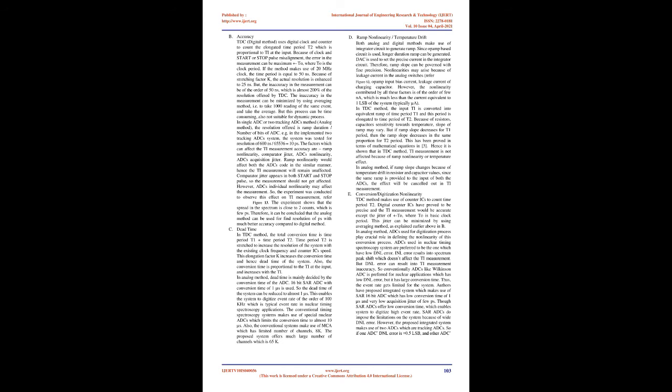In single ADC or two tracking ADCs method, analog method, the resolution offered is ramp duration/number of bits of ADC. E.g. in the implemented two tracking ADC system, the system was tested for resolution of 600 ns/65536 equals 10 ps. The factors which can affect the Ti measurement accuracy are, ramp nonlinearity, comparator jitter, ADC's nonlinearity, ADC's acquisition jitter. Ramp nonlinearity would affect both the ADC's code in the similar manner, hence the Ti measurement will remain unaffected. Comparator jitter appears in both start and stop pulse, so the measurement should not get affected.